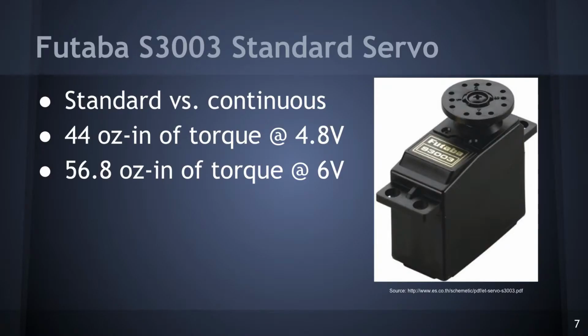For this project, we decided to use a standard servo because the LiDAR sensor needed to know where it was in the room when it mapped. Another reason we chose this servo is because the Arduino Uno can output a voltage of 5 volts. This servo can operate from 4.8 volts to 6 volts, making it ideal for our purposes.